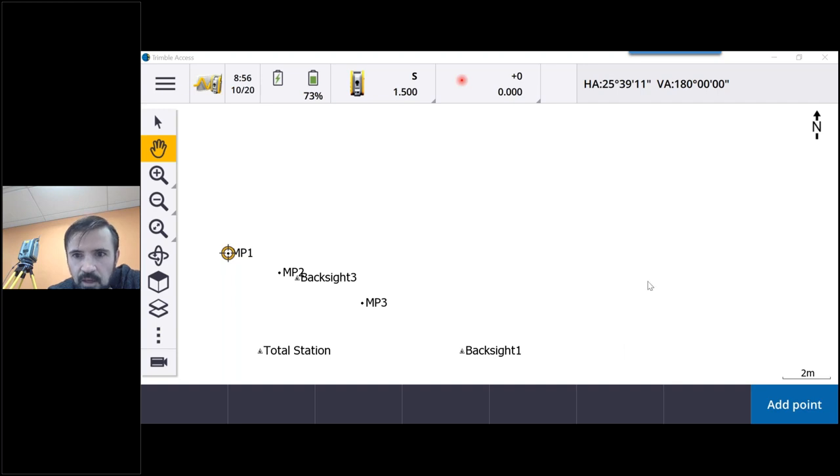Steve, you asked a question. Can the software be used in a situation where data is collected weekly, monthly, with independent setups as opposed to active monitoring? Yes, you can definitely, Steve. Actually, there's no real requirement, as long as you have the raw data. For example, if you're doing resections and you're measuring different monitoring points, they can be the same monitoring points, they could be other monitoring points. All that data can be imported into TBC, and it can be combined as well, Steve.